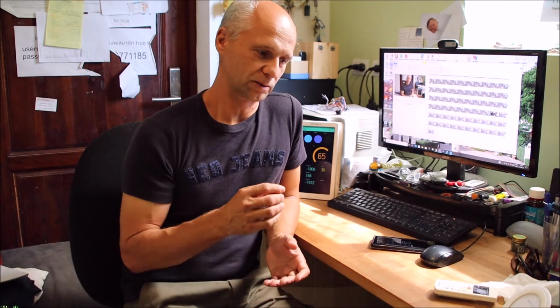I had problems, for example, with some freezing displays, but that was on the prototype. The connection's very bad there, and if some commands are dropped, it could cause the controller to freeze. So the biggest challenge, before I had Wi-Fi, was Modbus.